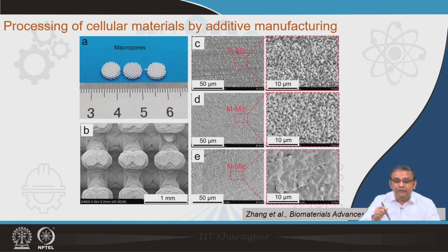Also, if we see the microstructure, we can see small pores. What we obtain over here after the final sintering, these fine pores in image D or image E, are the GUP pores which we are unable to control, because they depend upon the final sintering. That means it depends upon the sintering atmosphere, the sintering temperature and time. All those parameters will control these geometrically undefined pores.